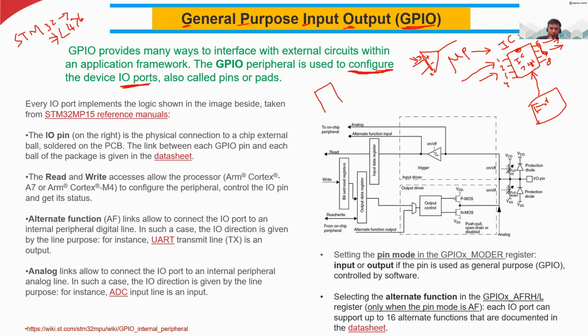For example, if I have the microcontroller here, I have so many pins. In the tool, it can be CubeMX or CubeIDE. In both tools, you will see this microcontroller. Of course, you will see many pins, but for example, you just left click on this one and then you will see a list of, for example, input, output, timer, ADC, like that. You can just click on whichever you want. Then that one will be set to this pin. That is called general purpose input output configuration.